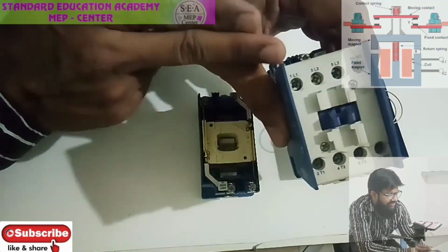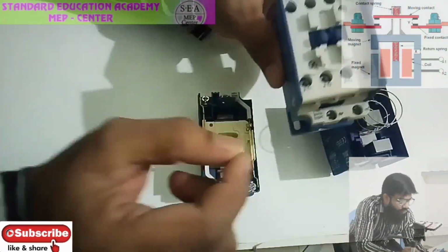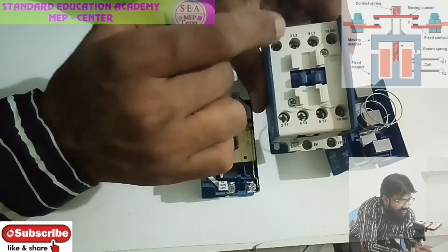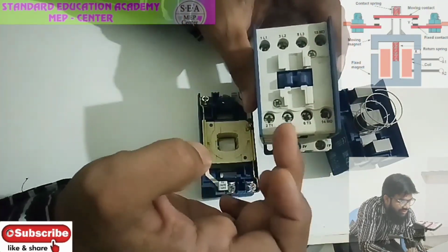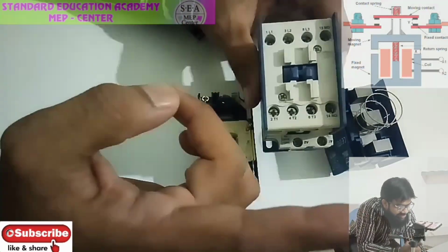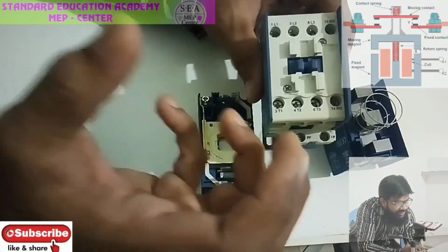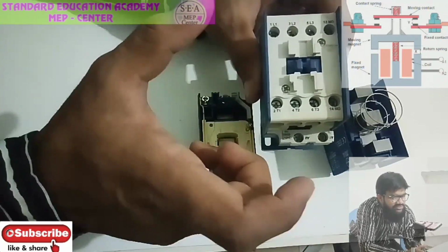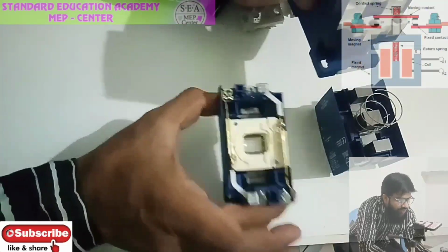You can even say it as RYB input, RYB output. When the coil is energized, a contact will be created from L1, L2, L3 to T1, T2, T3, and within the video I'll be giving you an animation, such that you can get a brief idea how a contactor actually works, how the terminals are getting interlocked, and how they are locking due to the coil operations.